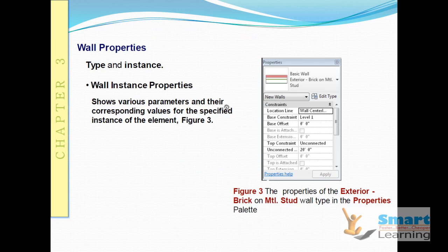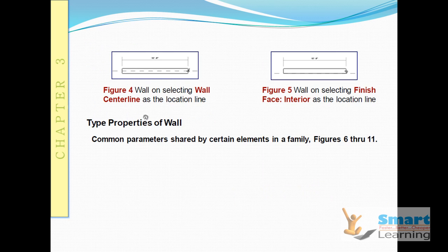Finally you have different wall instance properties that you can set: the constraint, the base offset, how much the height of the wall is, and all this you can control by using different level tools. And for different types of walls, there is a basic generic wall, or you can have a structure with a composite wall structure, having interior or partition properties.